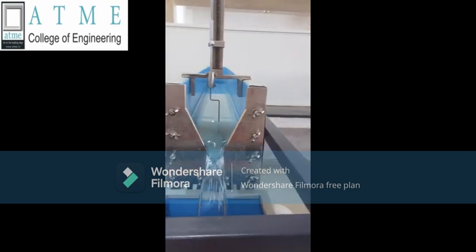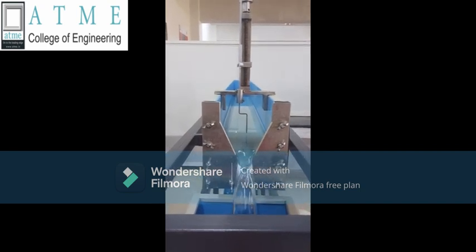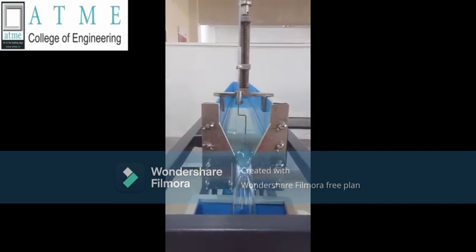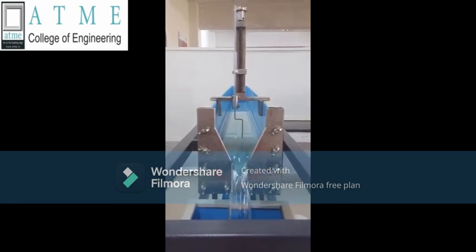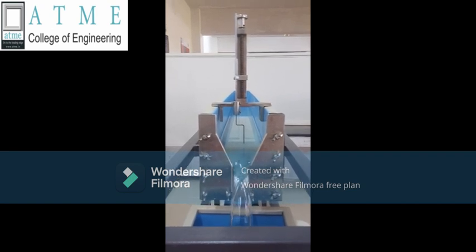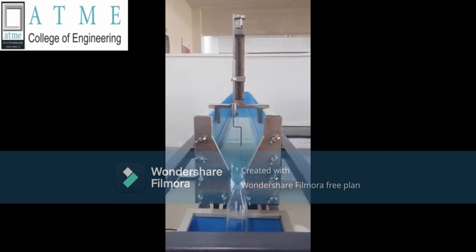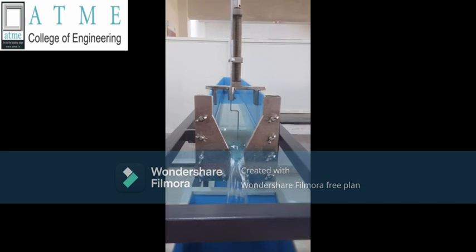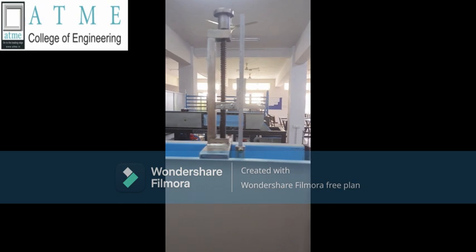The discharge is reduced in a channel. We are calculating H for medium discharge. Again, after some time, you have to adjust the point gauge in such a way that the tip of the point gauge has to touch the top surface of the water. After adjusting the gauge, again note down the height of the water as H2.